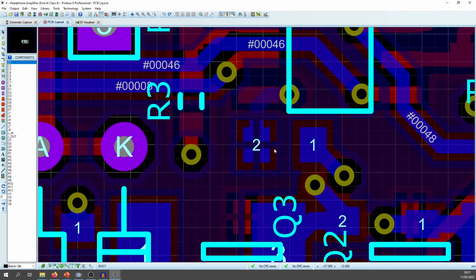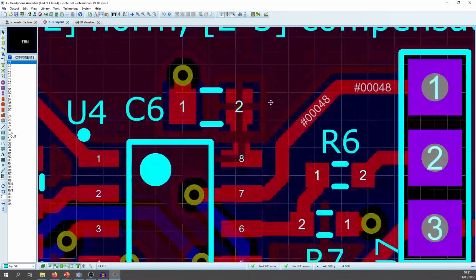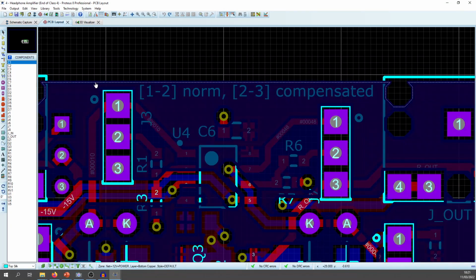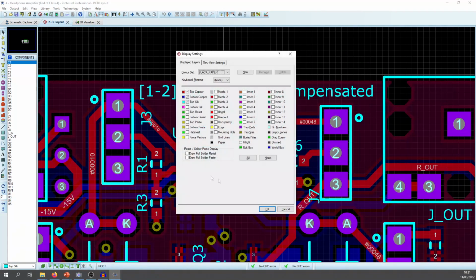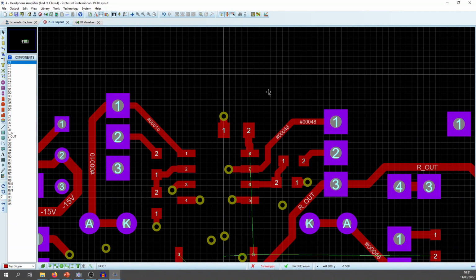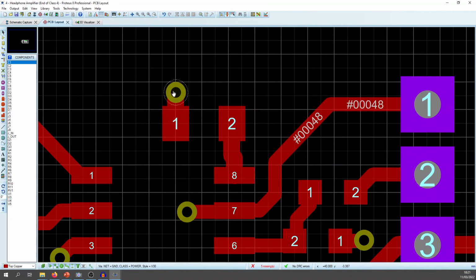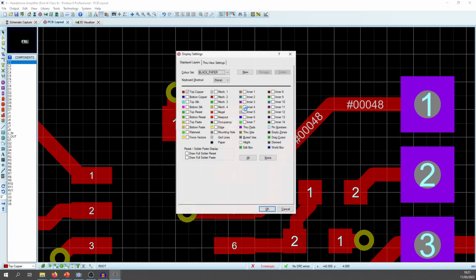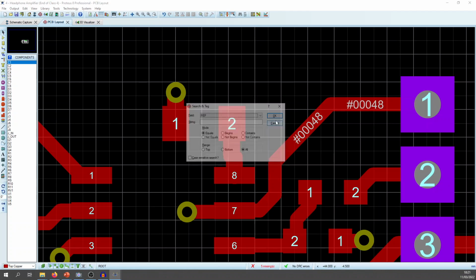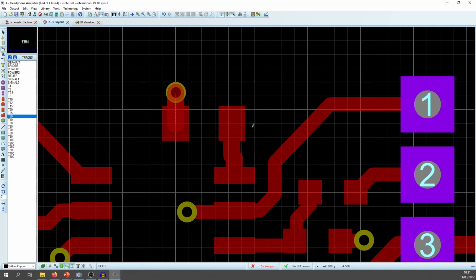Because I put this on the bottom layer and this other one on the top layer, it'll be easier if you imagine this power plane isn't there. So if, for example, let's choose one of these, turn top copper on. I'm just going to get rid of this power plane for now. Power comes into the decoupling cap. It goes, sorry, that's ground. Power comes in from the nets. So what would actually happen is you would have power coming in to the decoupling cap. Okay.